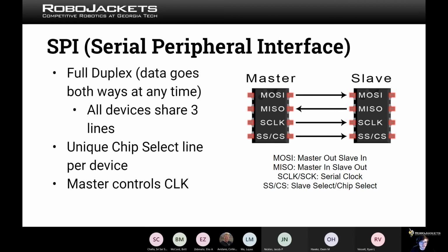And then we have three devices, or the devices share three lines to enable this. There's always one line, being a wire or a PCB trace, whatever. They share three connections. So the one is MOSI. We have the term master and slave. The master can control the bus, and then the slave responds with information based on the requests of the master. So we have MOSI, which is master out, slave in, acronym, and then